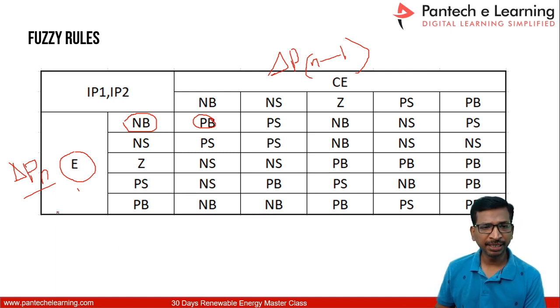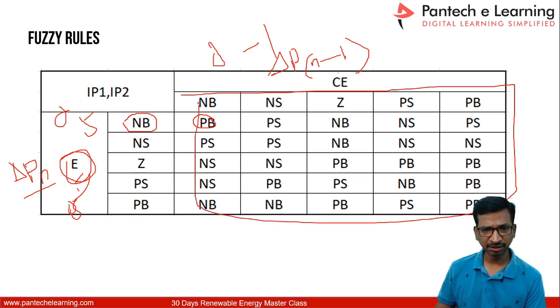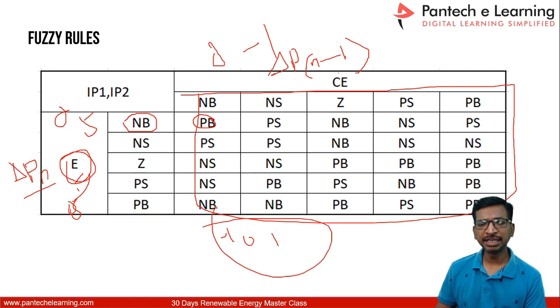Here if you take a 0 to 5, the 0 is nothing but negative big and the positive big is nothing but the 5. Within this range you have to divide, 0 to 1. Like this we have to assign these common two input variables for the fuzzy logic unit, error and change in error. Here are the outputs, these are all the output functions. For that you can use minus 1 to 0 or minus 1 to 1. Within this range, automatically the rule will get enabled.